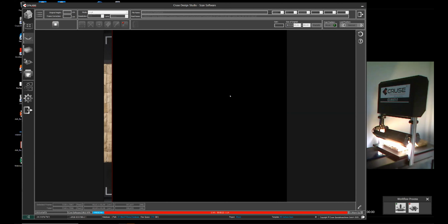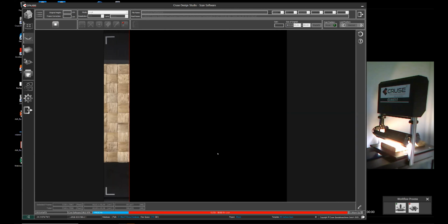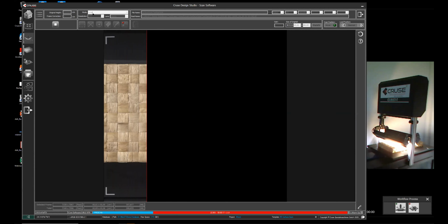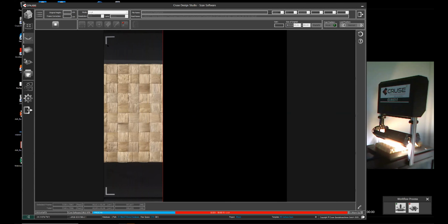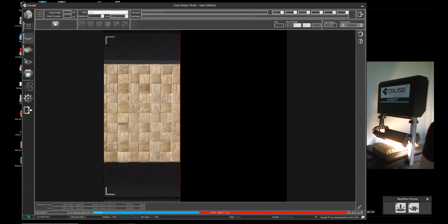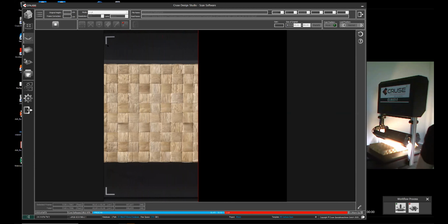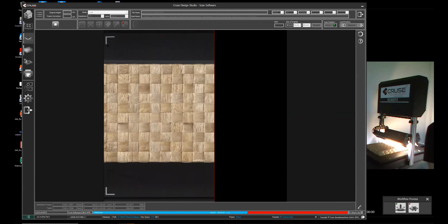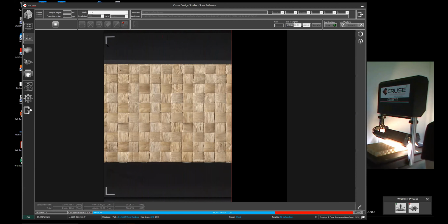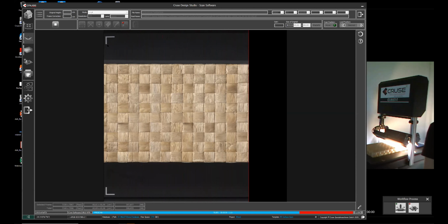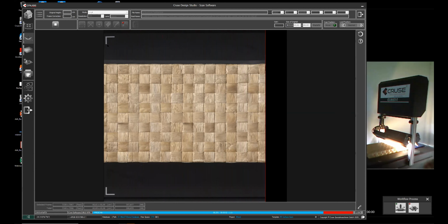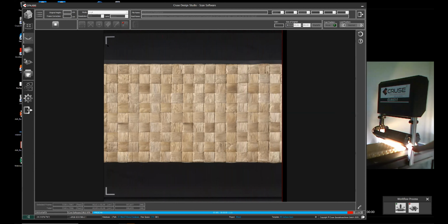Okay. So you can see already the scan speed is very fast. This is a light angle device mode, because for 3D surface scanning we need to scan in 4 different light directions, and this is what I will do now. For this we are using our light angle devices, which you can see here in this scanner, some lens plates which slide into the lamp.